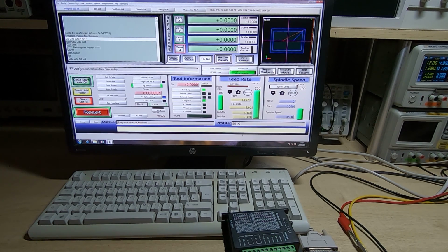So I'll do that. Just to repeat that, because it is the basis to how all this works: we click on start, the program runs through till it finds an M6 tool change macro. It then runs the M6 start macro, goes through whatever's in there, and even when that macro is finished, MACH3 will sit and wait until you click the cycle start button, and when you do that, it will run the M6 end macro. So what have I got in those?